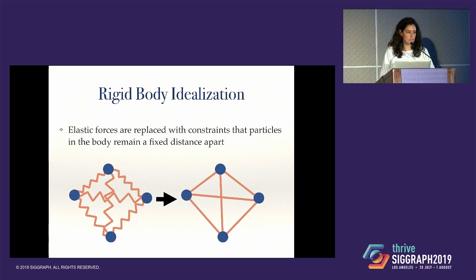because those stiff springs make information travel very quickly through your system. If information is traveling through your system very quickly, like if I push on the podium over here, if I push hard enough, the whole podium is going to move. And what that means is that I pushed over here and information traveled over here right away, pretty much. Whereas if this was really squishy and I pushed over here, then there would be some local deformation around this area, but it might take a long time to get here, or it might be completely damped out before it gets here. So if you have very stiff springs, information travels very fast, and you typically will either need very small time steps in your simulation to capture that traveling information, or what's called an implicit method, which is very closely related to small time steps.